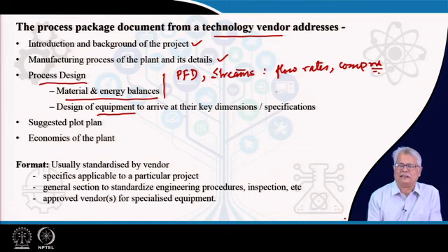Mind it, GA drawings are not fabrication drawings. In fact, GA drawings are used in order to assemble things after they have been fabricated. Fabrication drawings are prepared separately.